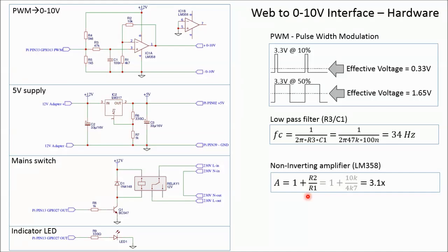Not all op-amps can do that. Please remember to ground the pins 5 and 6 of the second amplifier in the IC, otherwise the IC may start oscillating. Then there are R4 and R5. They provide an initial dim value of about 75%.